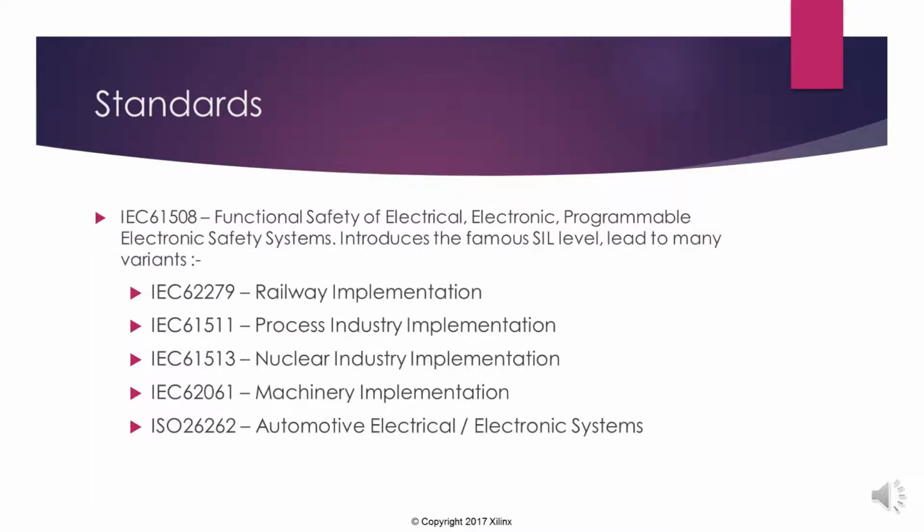To help us address some of these challenges, there are a number of standards in the world. Perhaps one of the most famous is IEC 61508, which is an electrical functional safety specification. There are also a number of sub-specifications that have come from this, very specifically industry dependent, going from railway all the way down to automotive. For a lot of aerospace applications there's also DO-254 and DO-178, but a lot of the techniques we're going to talk about are very similar. To keep this simple and not take it on for 2 hours, and only 1 hour, I'm going to particularly focus on IEC 61508.